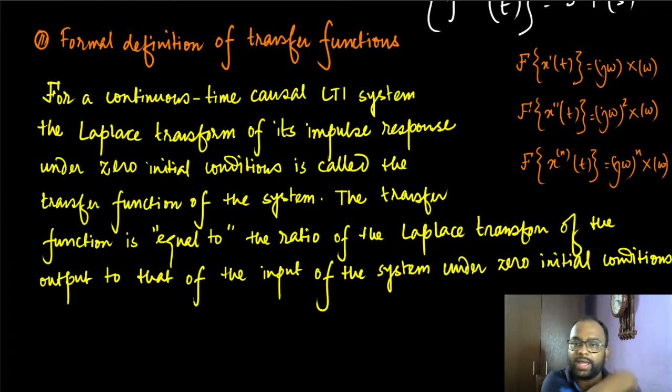Once again, just to go back, the transfer function is defined as the Laplace transform of the impulse response under zero initial conditions. Conveniently, this is also equal to the ratio of the Laplace transform of the output to that of the input under zero initial conditions, again for continuous time causal linear time invariant systems.